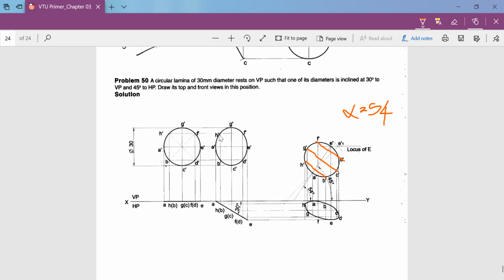Once you draw the perpendicular line through this reference point, then go back here from this first line to edge. What is the distance it is? So this is a point A, so this is the first line what you have constructed. So from the reference point here, measure the distance from there to edge, how much it is, you cut an arc. Similarly, from the same point to B dash, how much it is, you refer and you cut an arc.